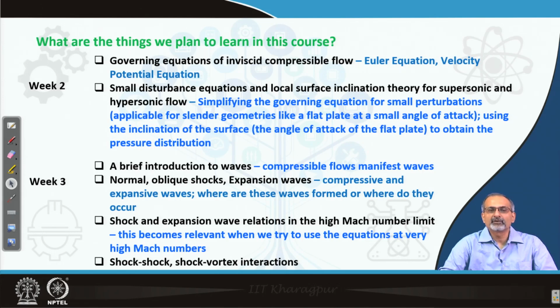If you may recall from your earlier exposure to fluid mechanics, in inviscid compressible flows we basically deal with Euler equations, and when we make certain simplifications, idealizations, we may be talking about the velocity potential equation, and we can talk about small disturbance equations and local surface inclination theory for supersonic and hypersonic flows.